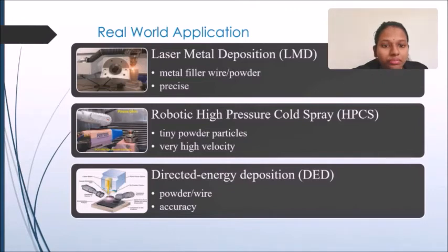And also a recent development that has been looking at repair, manufacturing, and remanufacturing applications uses a robotized cold spray cell equipped with a 6-axis robot and turn tilt table, which we're seeing in the picture, and this is used to address complex part repair requirements such as iron cylinder heads and also aluminium mold tool repair.